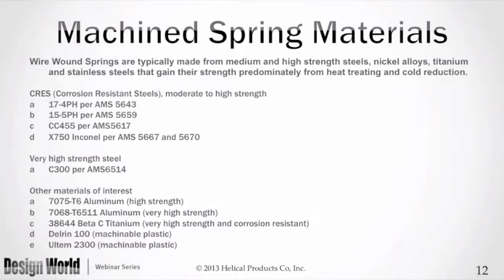The size, we skipped, no we didn't. Materials that springs can be made out of are numerous. The wire people have a whole set of special wires that get used, and they're very successful with that. The machine springs, on the other hand, stay pretty much with materials that get their strength not from cold working and not from quenching, but rather from an aging. And that aging is usually around 900 degrees, whereas those other activities sometimes will be higher than 900 degrees.